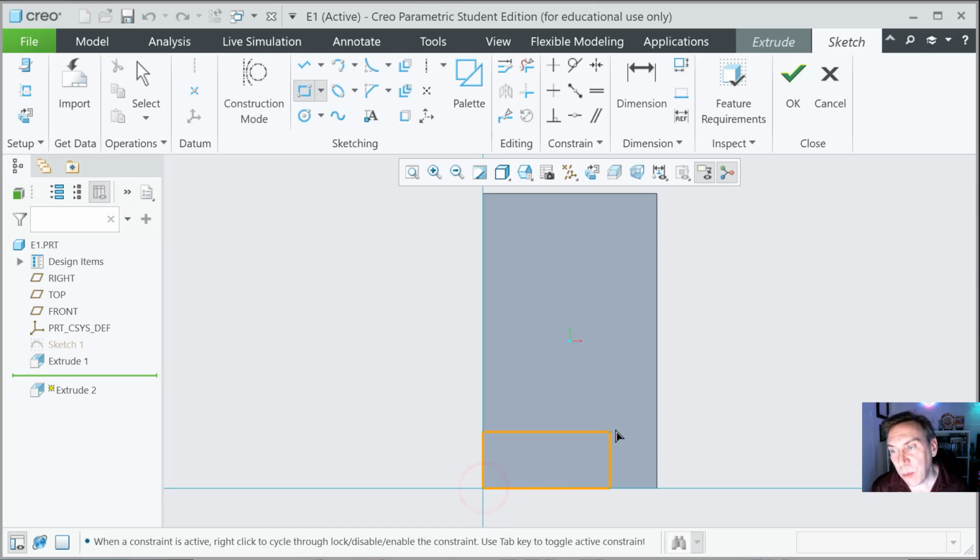Click. Now move your pointer over to the right, and you'll see when it gets to the edge, it highlights the edge. It activates it, so it will snap to it. Look there in that little bubble to the right of it, it's finding a coincident relationship or constraint on that edge. So if that edge ever stretches, and change always occurs in modeling, so will this. And sometimes you want that, sometimes you don't, but we want it in this case. So go ahead and click.